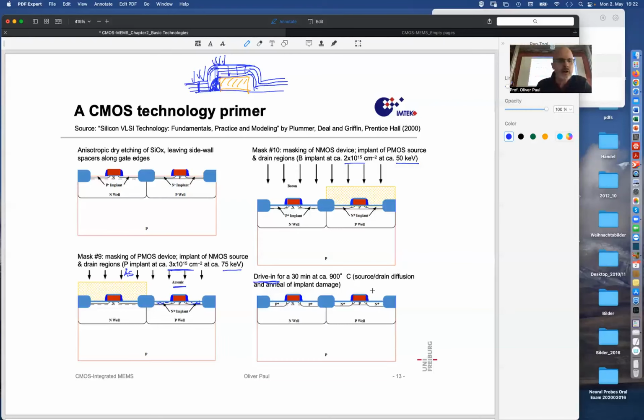Yeah. So now we have the situation with the gate oxide still there. We have these source and drain diffusions of the right doping polarities on both sides, and basically the transistor is kind of ready, but the source and drain need now electrical contacts to bring in charge carriers that can flow underneath the gate or be blocked by the gate.